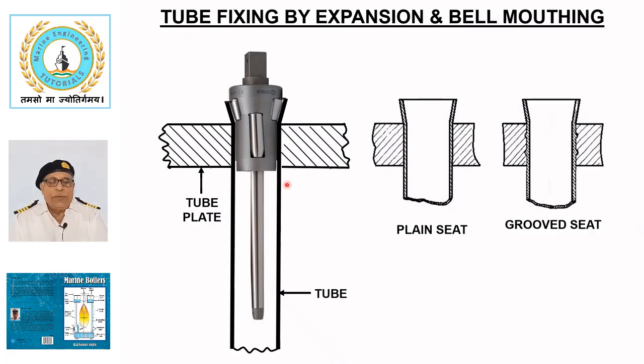Before fixing the tubes in the seat, both the tube plate seat and tube outside should be thoroughly cleaned to remove any foreign particles which may cause leakage. The tube is then inserted in the tube plate and must extend in the drum or header by at least 6 mm for bell mouthing, which is 1 mm for every 25 mm of the outside diameter plus 1.5 mm.